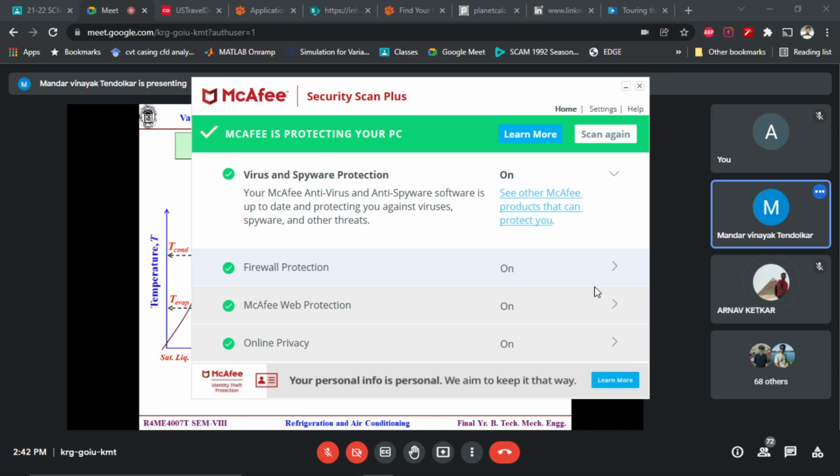Yes, sir. Okay, so A1 is the extra part in the denominator, that is compressor work. And A2 is the loss in the numerator, refrigeration effect. So your COP is bound to reduce. Correct? In the numerator there is a loss, in the denominator there is increase.